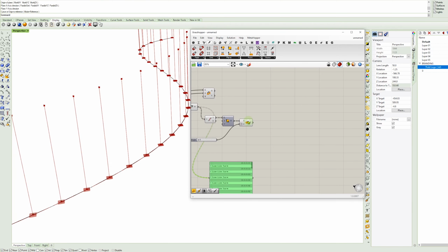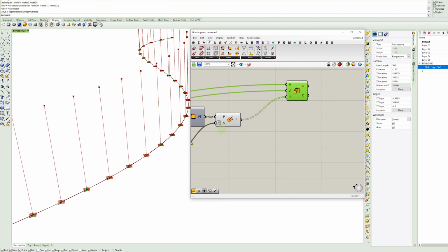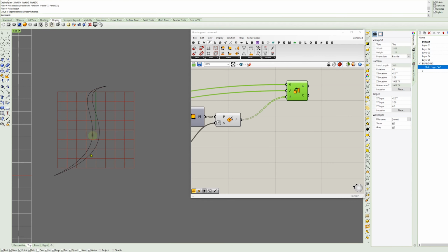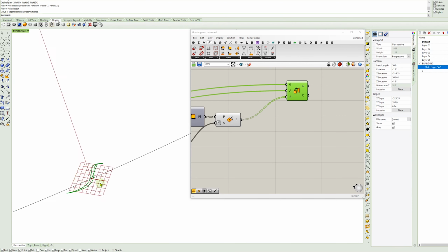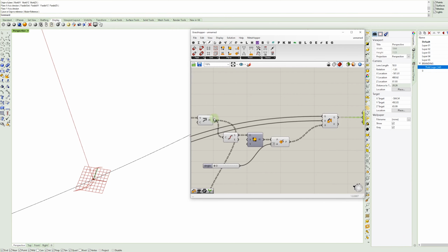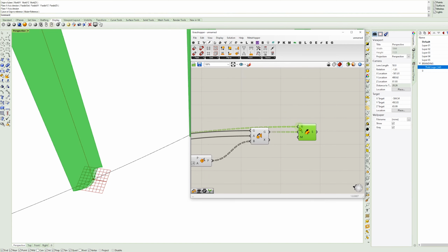Okay, so now we've got planes, and we're going to map that profile up to the planes. You can see if we look in, Y is up, X is to the right, that's aligned with the Y up, X to the right that we drew, and that's going to be adaptable as I change things. Essentially all I need to do is map that on, and then I can double click, type in sweep 1, and use my section profiles for S here, and then the rails are going to be the polylines we used way back here, plugging that in.